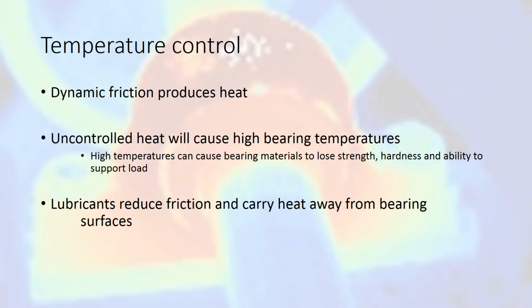load. If you have a large amount of heat that needs to be taken away from a bearing, we can circulate larger volumes of lubricant, and that heat can be carried away from the bearing and discharged into a heat exchanger of some sort.